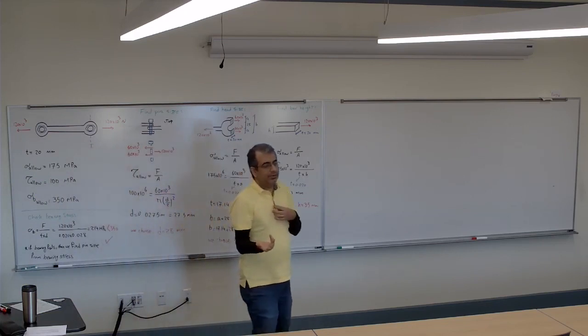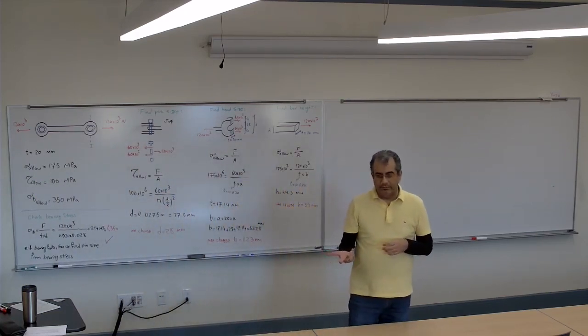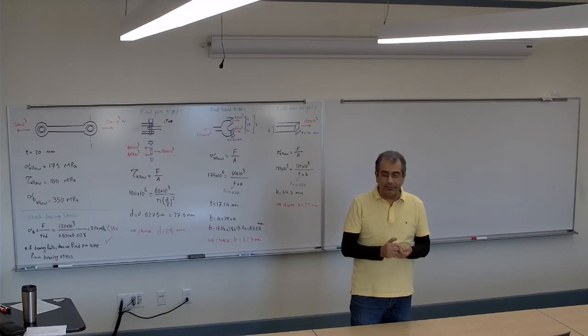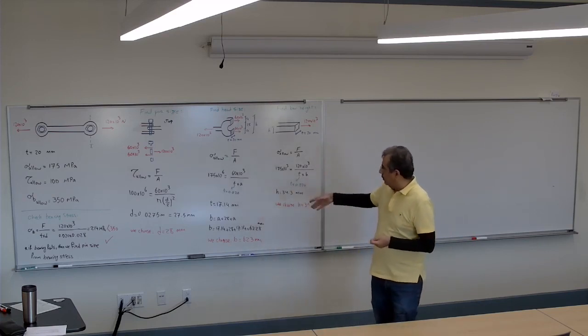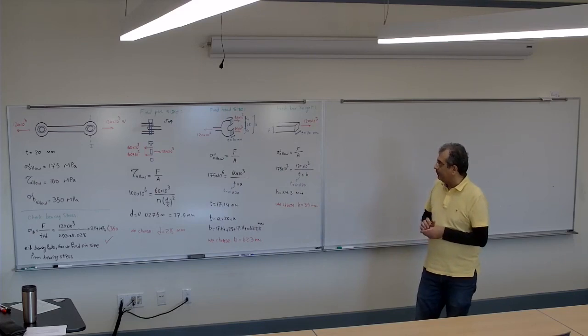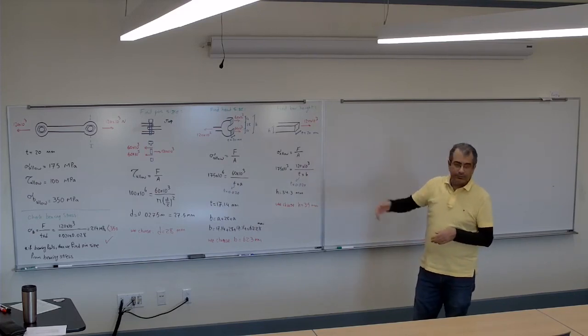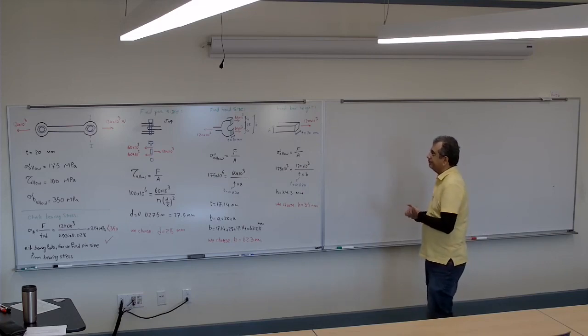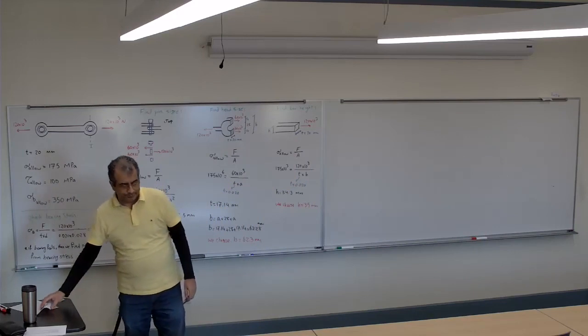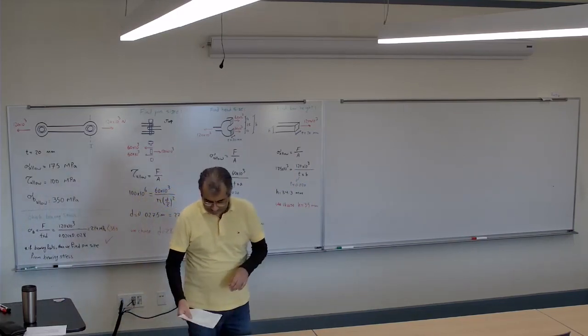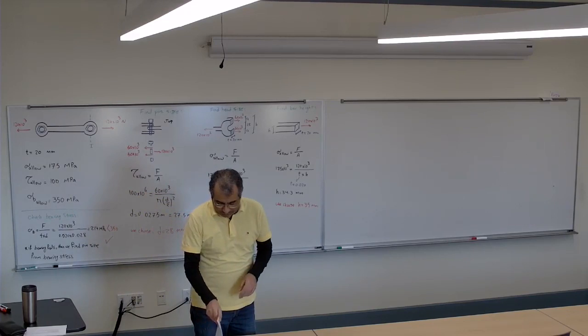So that is the very simple procedure to design a member. We have to go and find the stress in every possible point that it might fail, and then design all the sizes and thickness in a way that we make sure we always stay below the breaking point. So that's the normal and shear stress.